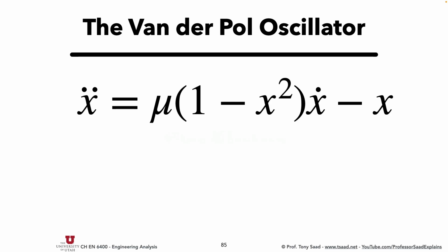And you have this constant coefficient, so you have x squared times dx by dt. So it's a very nonlinear spring mass damper system. It's a classic problem. They study it in nonlinear dynamics, and x here is the position, and therefore dx by dt is the velocity, and mu is just a damping coefficient. How much resistance does this oscillator have towards displacement, making it displace?